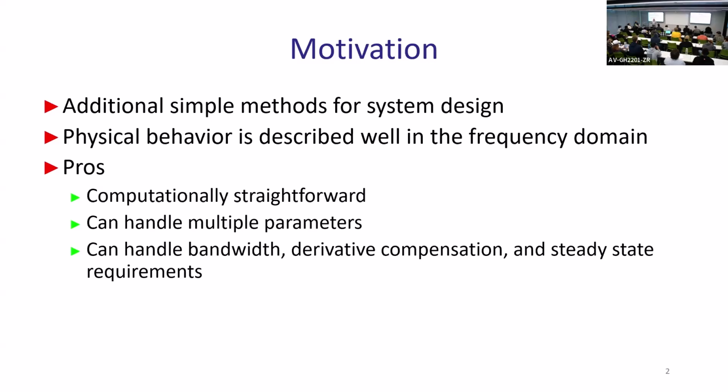Derivative, okay? And controllers with derivative need to be only approximated. And approximating that in the root locus domain is extremely complicated. So people just do not do that. In the frequency domain, the difference between a pole and a zero is just whether you're going up with Bode or going down with Bode. Still Bode, same thing, okay?